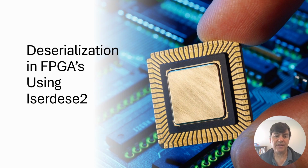Deserialization in FPGAs using ISERDESE2. The ISERDESE2 is a deserializer primitive available in all Xilinx 7 series devices. It's similar to the ISERDESE3 found in UltraScale FPGAs, but interestingly, the ISERDESE2 actually offers more features. That's right, in UltraScale they simplified the block and reduced the feature set.